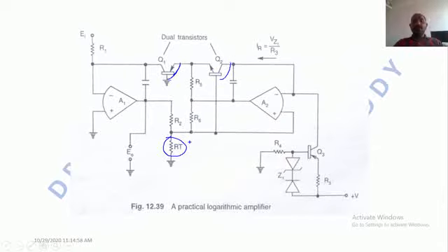Or I can say that the voltage drop across the RT is the potential difference between the base emitter voltage of this particular Q1 and the base emitter terminals of this particular Q2. So if I assume them as VBE1 and VBE2, then the voltage drop across this is VBE1 minus VBE2. Like that it is decided. Now the output voltage E0 is decided by the A1.